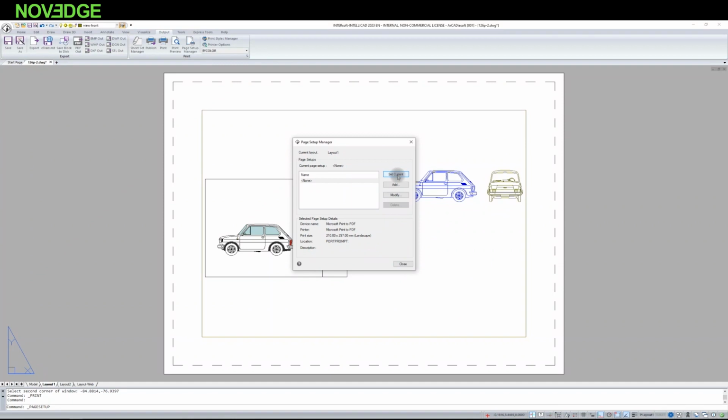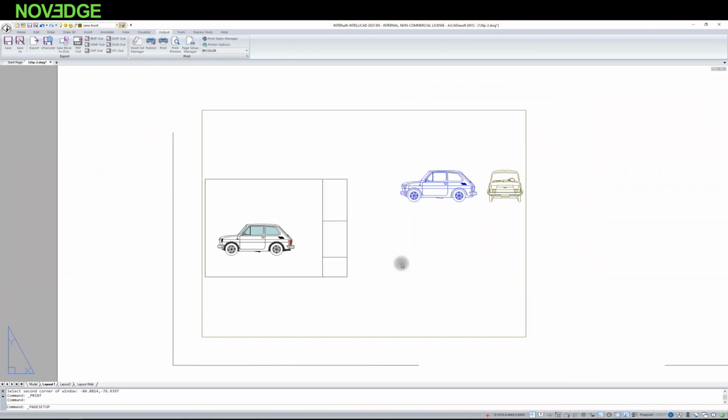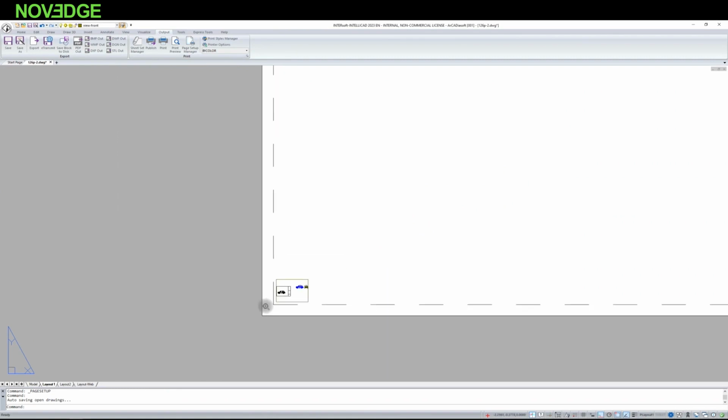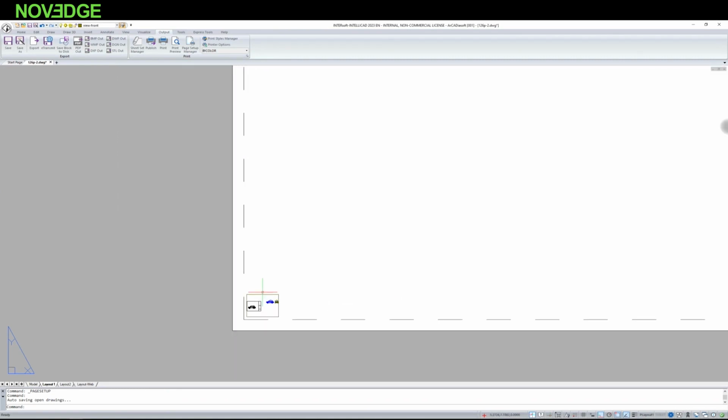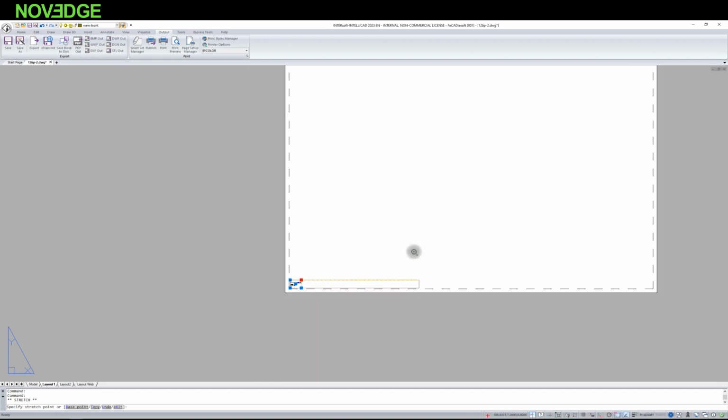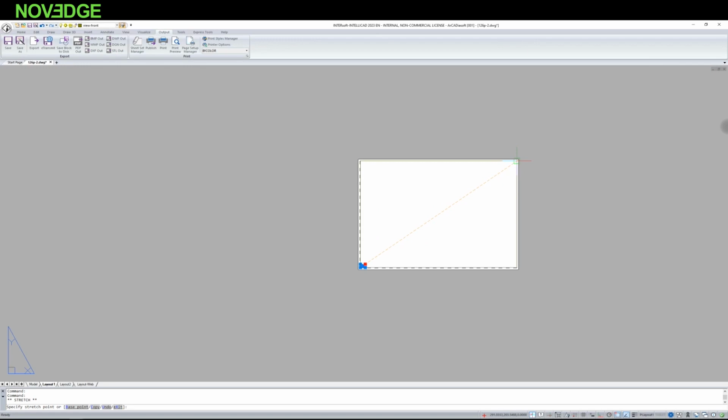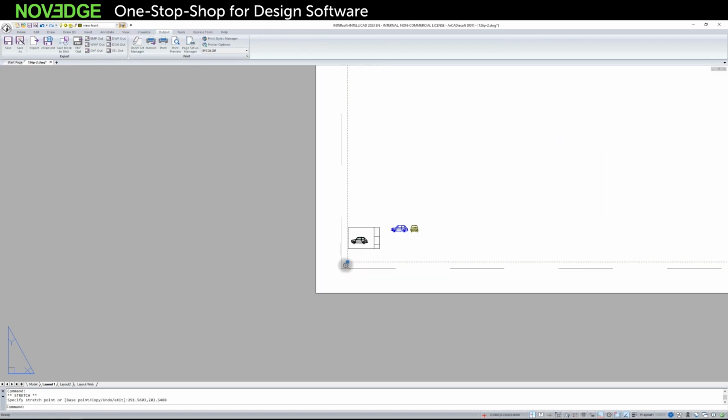And the sheet that you're actually going to print is this sheet. And now what is printed is what is in this viewport. Now I will select this viewport and I can enlarge the sheet by moving these handles. You could say that it is more or less so, and it would even be true.